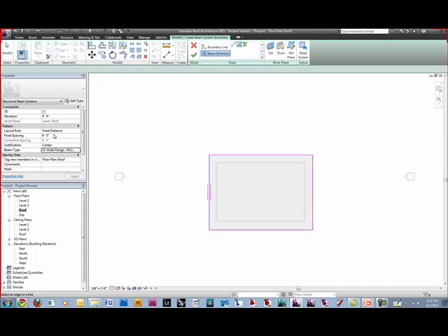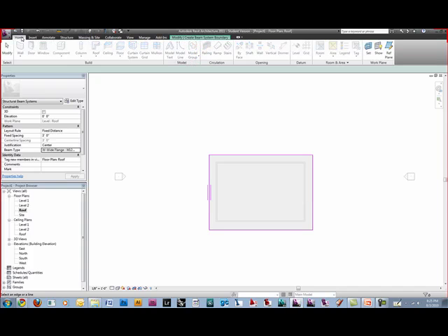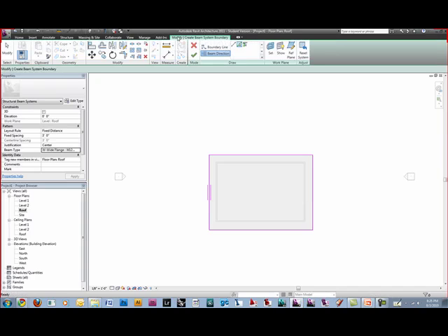So right now, if you look at our properties to our left over here, it'll show that they're going to be fixed spacing of 6 feet, and a fixed distance versus maximum spacing or fixed number or clear spacing. So we're going to do fixed distance, which sounds good, but let's do 3 feet instead of 6 feet. Just get some more in there. And then instead of this beam type of W flange, W12, we actually don't want that. We want something like a wood beam. We don't want W12s on a house. So what we need to do is actually load another family, but it's not going to allow us to until we finish this. So let's just finish this first, and then we'll go back and we'll change this to wood beams.